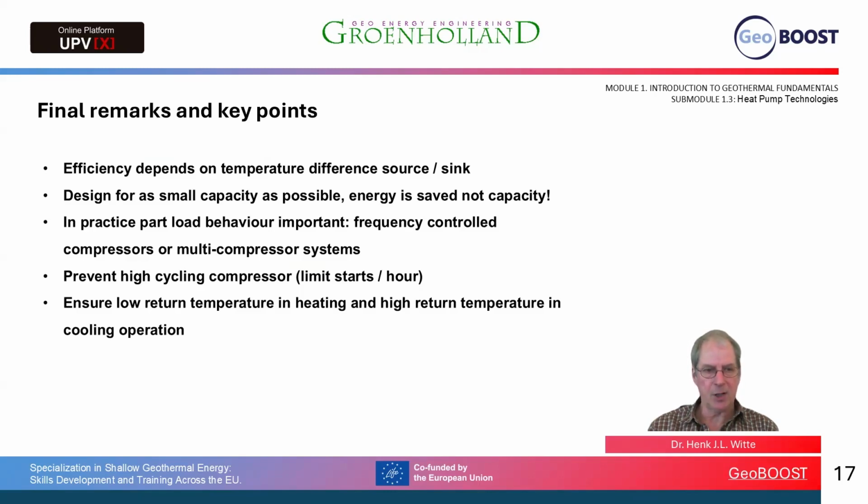In practice, the part load behavior of the system is very important, and this means that we would like to use either a frequency-controlled compressor or a multi-compressor system to match the capacity of the heat pump system with the actual demand side of the building. We would like to prevent also a high number of cyclings of the compressor start-stops.